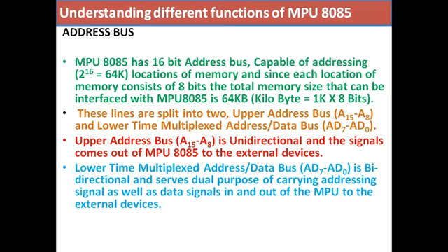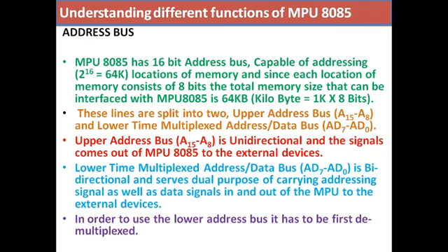It can carry address, it can also carry data, but since it is time multiplexed, if we want to use this bus, we will have to demultiplex it, and demultiplexing is carried out using demultiplexers and a signal called ALE.